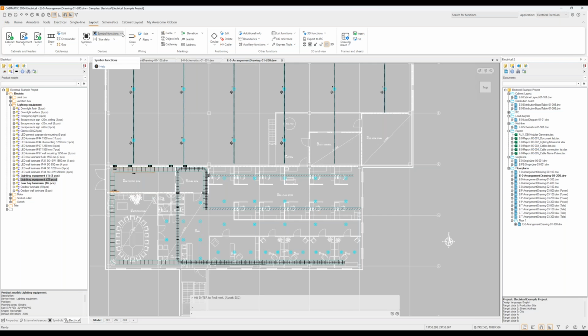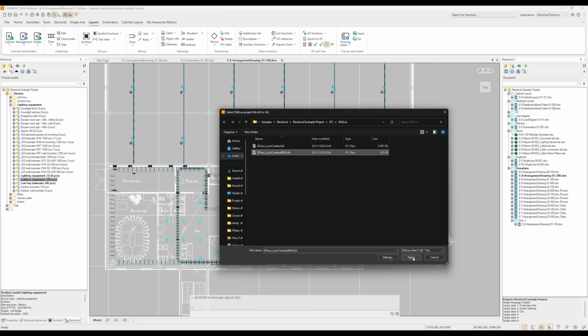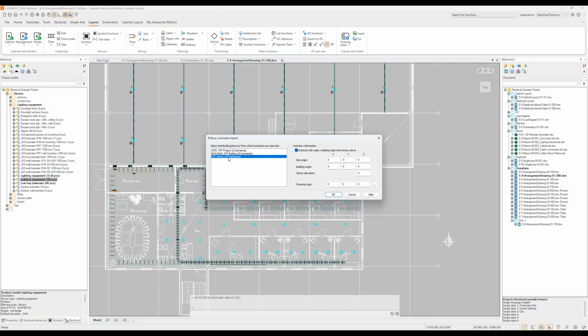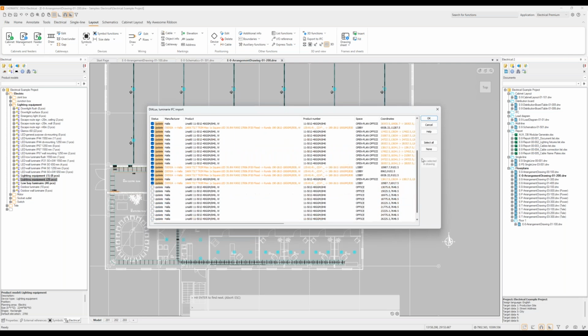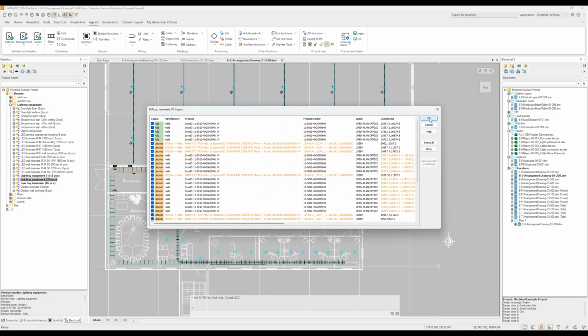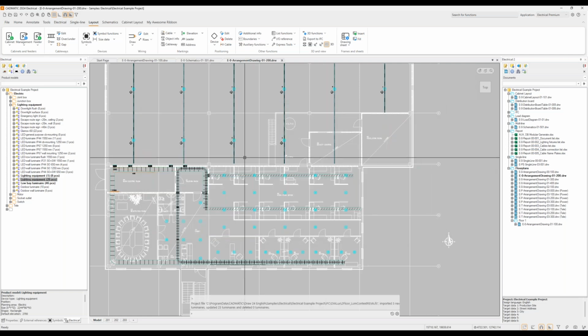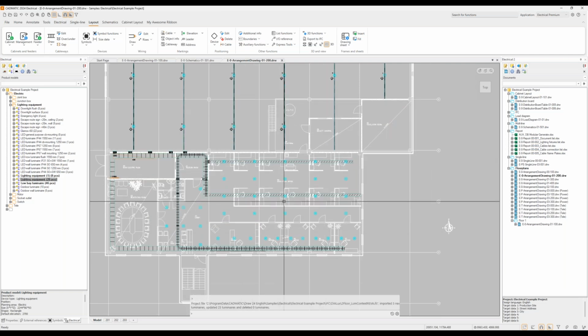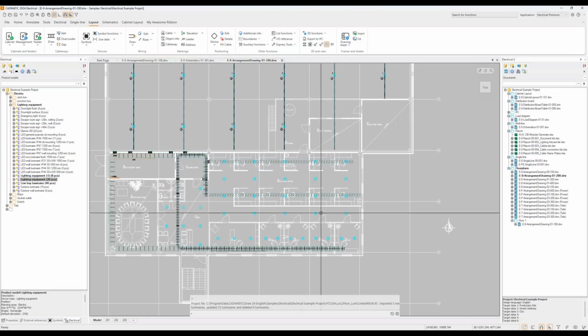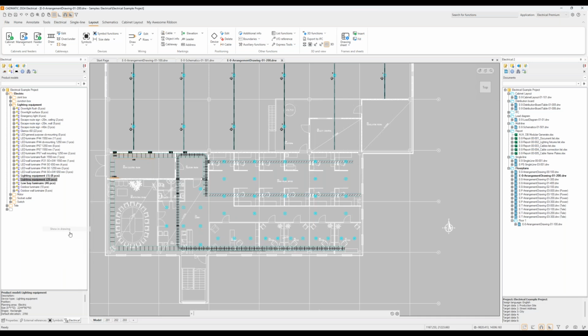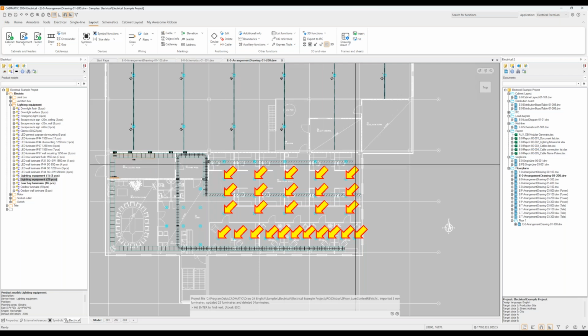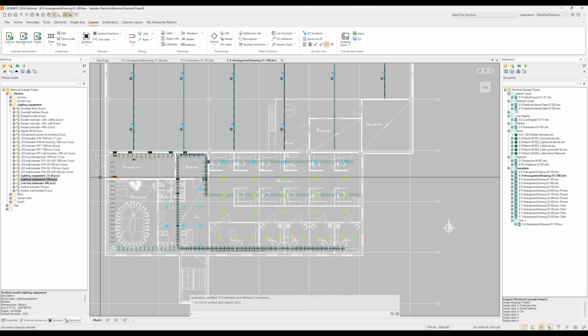So in case you need to update the same IFC, you made a new calculation in Dialux, you want to import the new one, you bring in 39 luminaires, select OK. There are some updates in it and so forth. Select OK. And now they have changed a bit, and now you can see there are a few more products here that were not listed before.